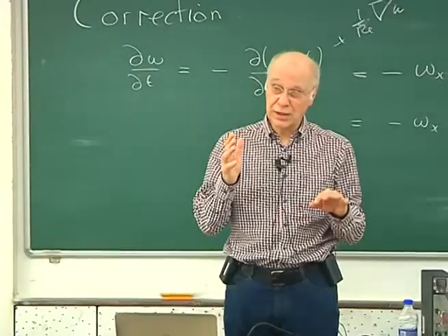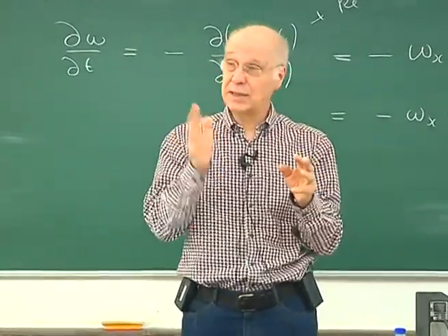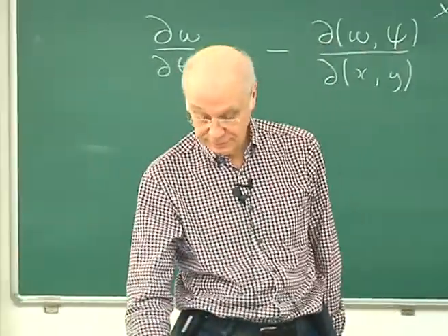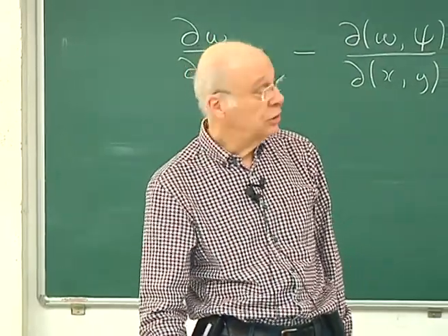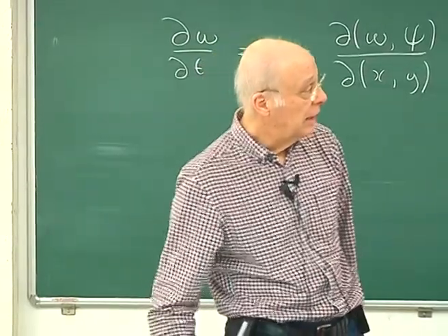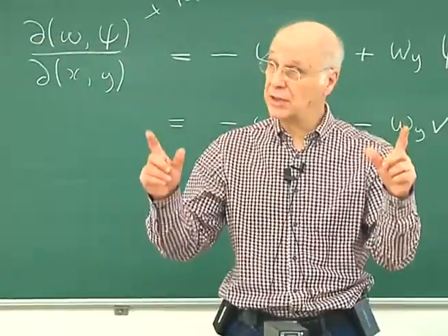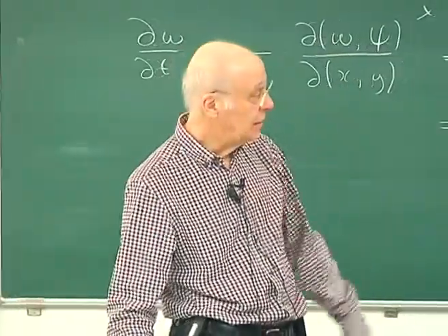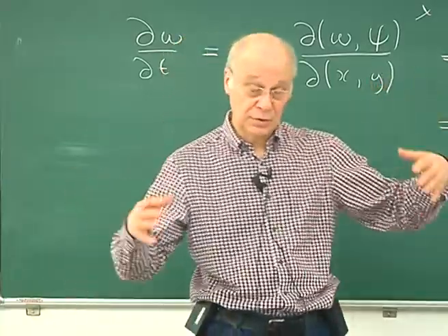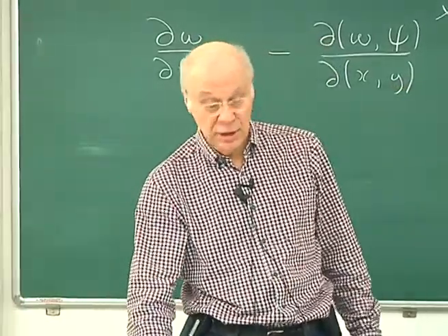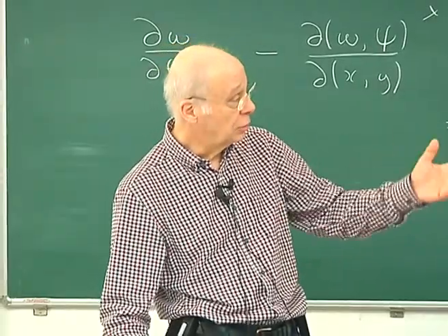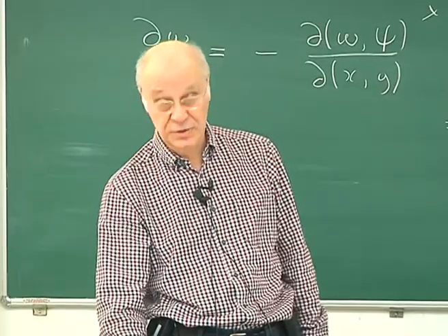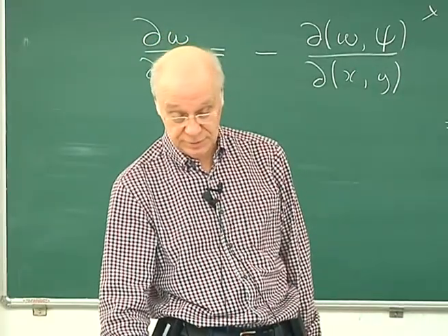So there would be a quartic term, which would be xi squared eta squared, but there wouldn't be any other quartic terms. And you can rig it so it takes the spot values at the vertices and at the midpoints with that extra freedom. If you use the same values at the adjacent rectangle, you have a representation over the whole domain which is continuous and has continuous tangential derivatives, but not continuous normal derivatives.